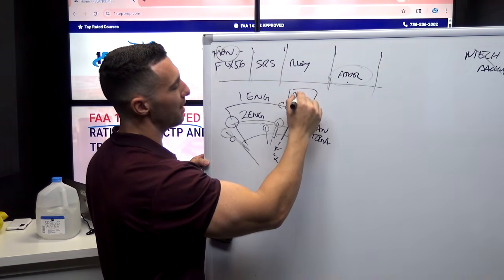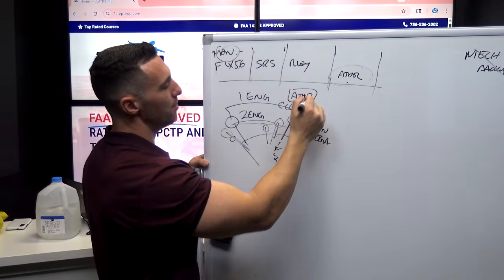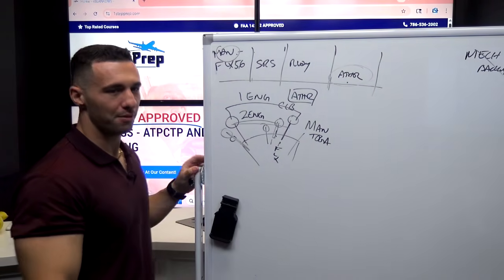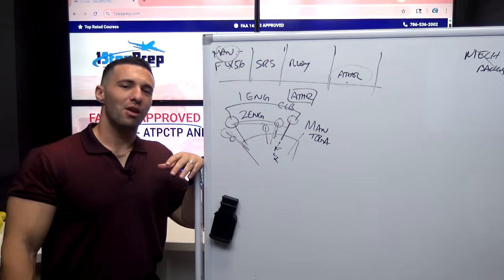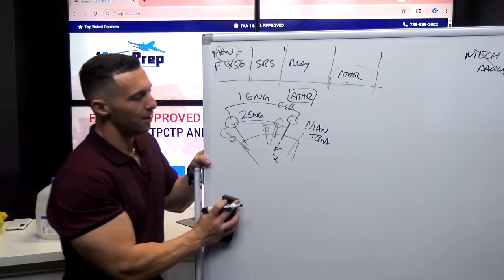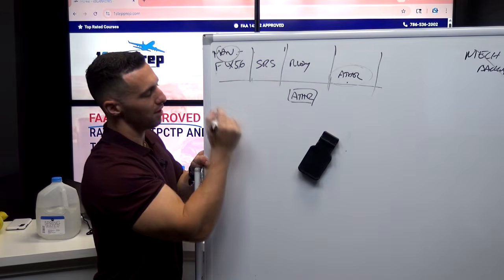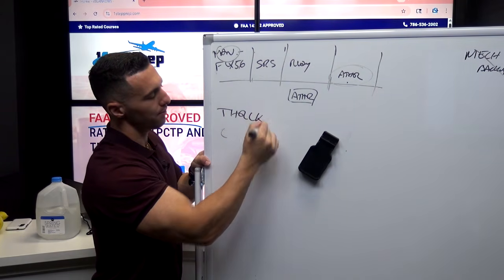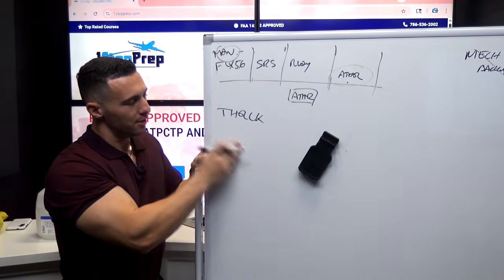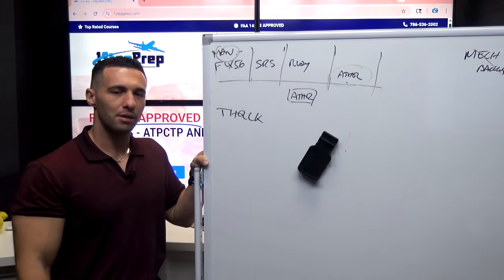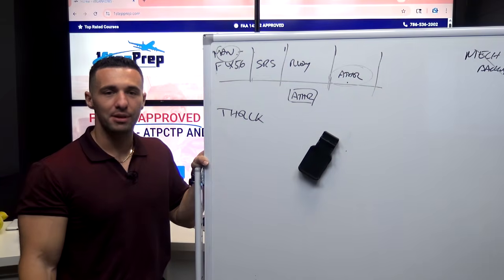Which brings me to my next point, which is the fact that this auto thrust push button is not the way that we disconnect the auto thrust. In fact, doing so will give you a fault, and the fault it'll give you is thrust lock, THR LK. And that means what it sounds like. The thrust will be locked at the last sensed value, whatever that happens to be.